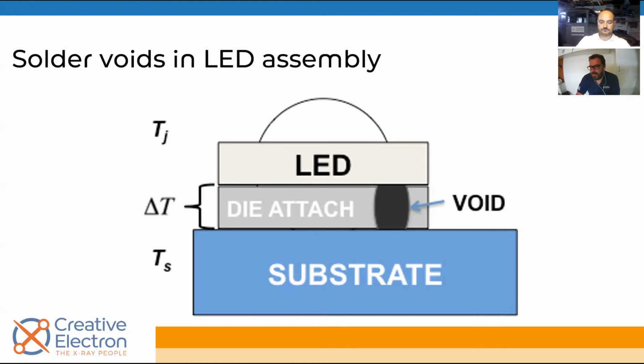And if you don't have enough solder, then the LEDs will fail. And they're probably going to pass all sorts of tests. They're going to turn on, they're going to do all sorts of electrical tests, they're going to be fine. But they could fail before they're supposed to, or before warranty expires. So if every single one fails before warranty expires, you don't have a product.